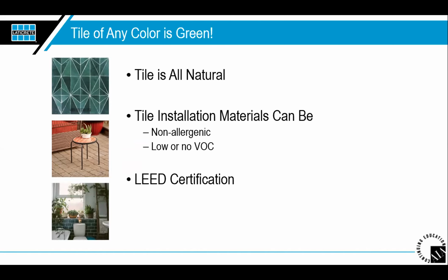LEED certification and compliance helps make sure that construction is environmentally and occupant friendly. Tile is a great choice for LEED compliance. Projects that use tile generally earn credits for low VOC products. Using low VOC installation materials can also earn credits. For example, 1 credit can be used for using low VOC installation materials, and 1 credit can be earned if the project is within 500 miles of an installation manufacturer's facility.